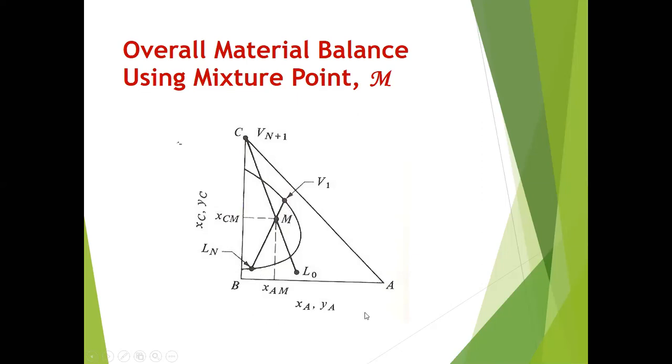So you have a rectangular diagram below wherein you can assign a point here for the raffinate. You go down, you turn right, you go up, and then connect. Once you connect the two and it passes right on M, then this would be your equilibrated phases, which is your V1 and Ln. Oh, I'm sorry, class. This is not the way you do it, by the way. Sorry. What should be equilibrated is the V1 and the L1, and it's not shown here, and it's a graphical thing.